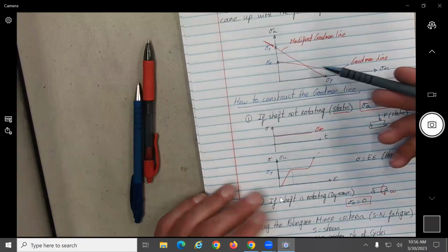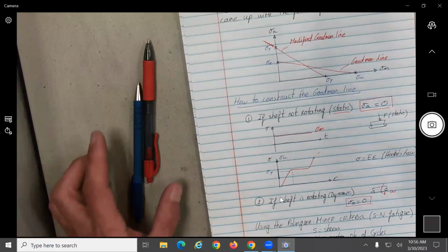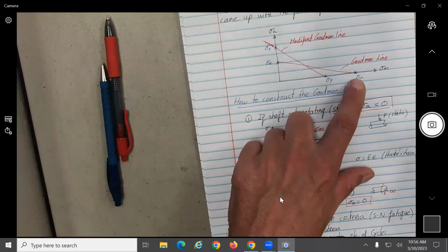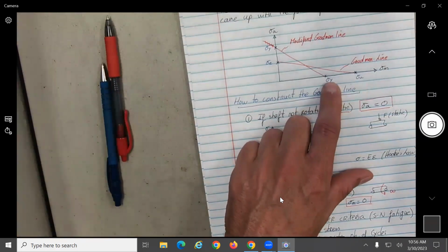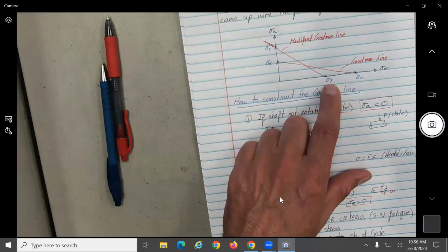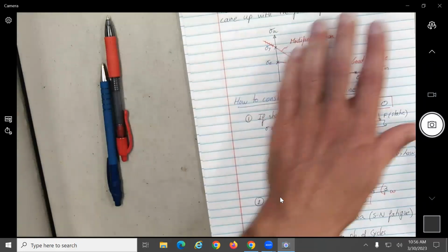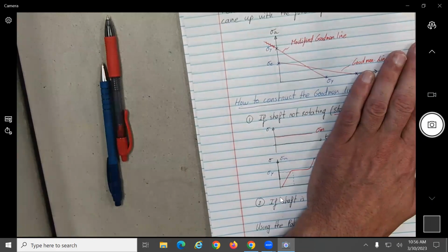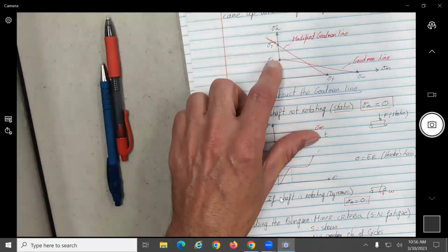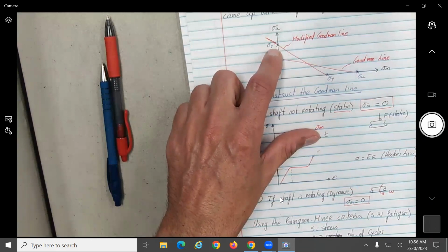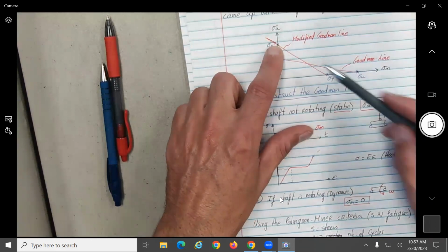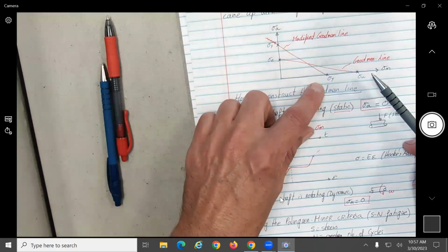Does that make sense? How did I come up with the idea? It's not rocket science. You just say, I'm first going to come up with this point by assuming the load is static, so I know it's going to break due to failure. And then on the y direction, say, okay, now I don't apply any static load. I use the Marin equation to find out what the endurance stress will be. He creates the points over here and just connects those 2 points with a straight line.